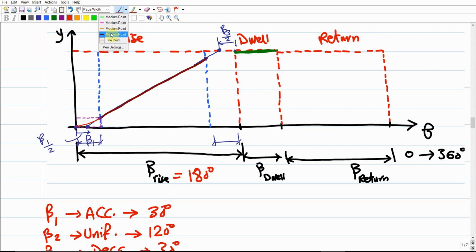It is highly acceptable as long as this period is too short or too small a zone, as already shown here. The same thing for this one: I can connect it with a curve that is opening down, indicating that this is a decelerating period. So we have another decelerating period and accelerating period, and you should understand that these two periods should be parabolic. In case these zones are too small, don't waste time breaking down the zone and repeating the procedure we explained for the parabolic functions up there. Instead, just connect these two points with a curve. It's highly acceptable and you can proceed with that.